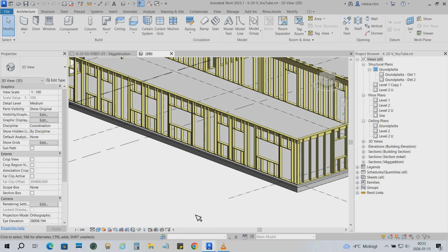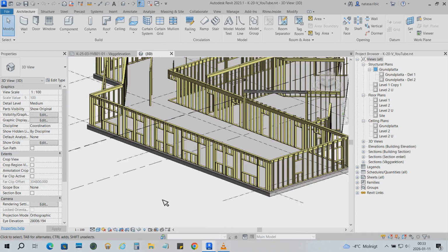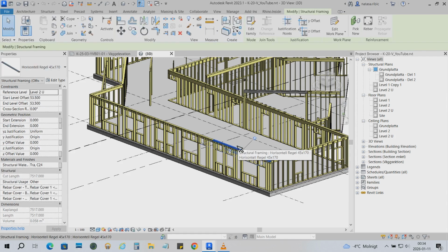I am going to focus only on one wall, that's this one. The wall is 25 meters. The wall is supposed to be prefabricated and then transported to the building place. Due to the transportation limits, each wall shouldn't exceed 8 meters. That's why we are going to divide the whole wall into 4 blocks. For instance, this block is 7.5 meters, the next block is 7.8 meters, then we have a block that is 4.2 meters, the last one is 4.37 meters.